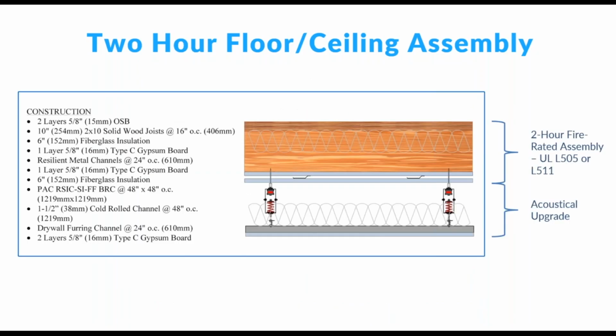So it can be really tricky, and finding a 2-hour fire rated design with acoustic isolators in it that will work for this situation is really tricky. There are some, but often what you wind up having to do is treat the acoustics and the fire separately. And that's what you'll see in these examples. So here we have a basic assembly design, and then we've built it for fire, kind of ignored acoustics, and then we've added spring isolators down below as an acoustical upgrade. And that's what we've done on a number of those projects in New York.